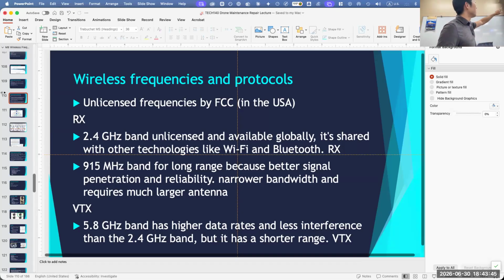There are a couple, those are licensed frequencies. You need to apply for a license and reserve that slot, because there's only so many frequencies available. They don't want people crowding over it. There's a couple of free-for-alls, the equivalent of your class G airspace, which is 2.4 gigahertz, 915 megahertz, and 5.8 gigahertz. Those are your unlicensed frequencies, meaning anyone can use them.